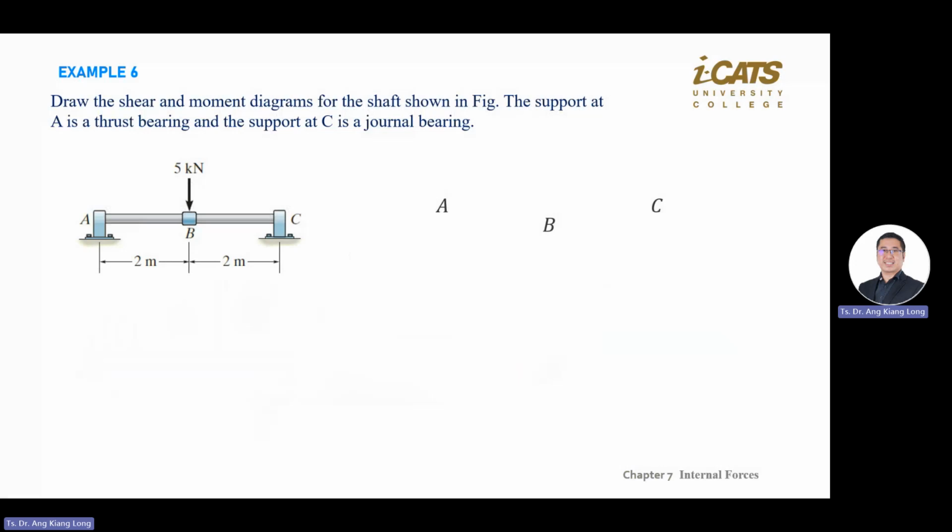No moment because this is a bearing. Then you know there's no horizontal force. AX equals CX equals 0. Then you analyze this one, and you know that A and C split similarly, so you know 2, 2. So this one divides in half. If not, then you can do sum of all forces equals 0, sum of all moments equals 0 to find it also. But by common sense, looking at this, you know what your AX and AY are.